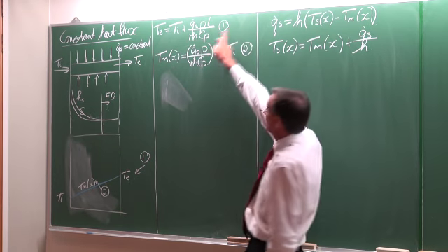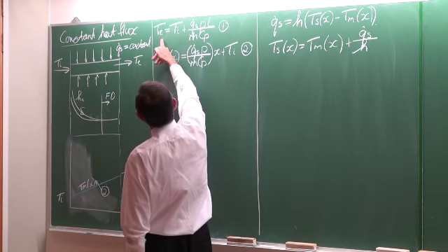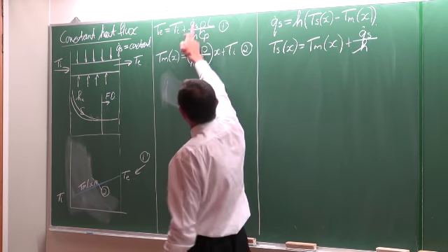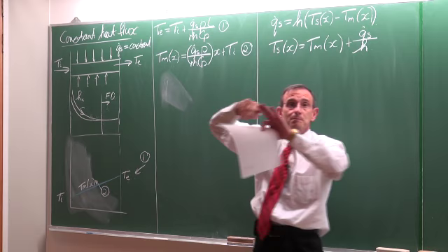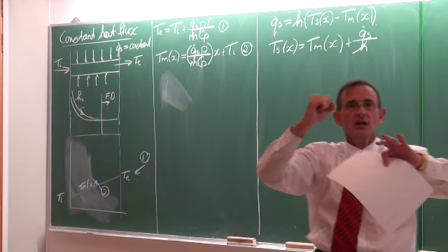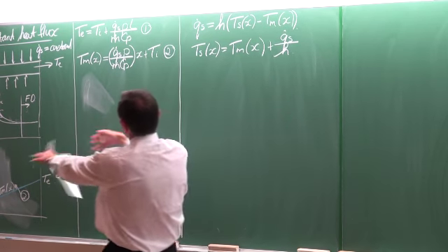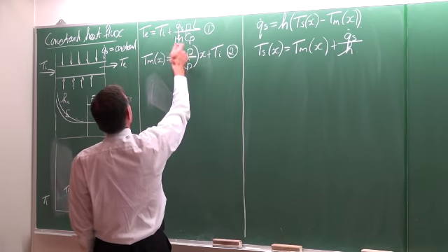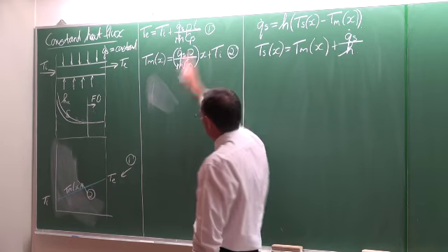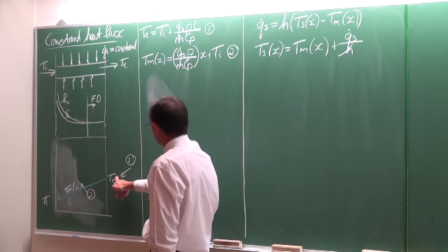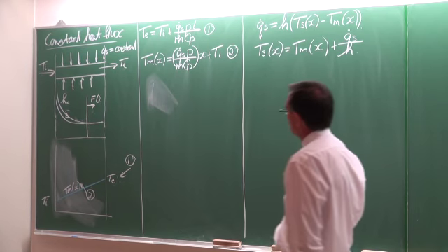And that is how we did it. It means the outlet temperature is the inlet temperature plus the heat flux multiplied by P, which is the perimeter. Okay, not necessarily a round tube, but it might be, multiplied by the length of the tube, divided by m-dot Cp. So the result of that was that we could get that temperature.